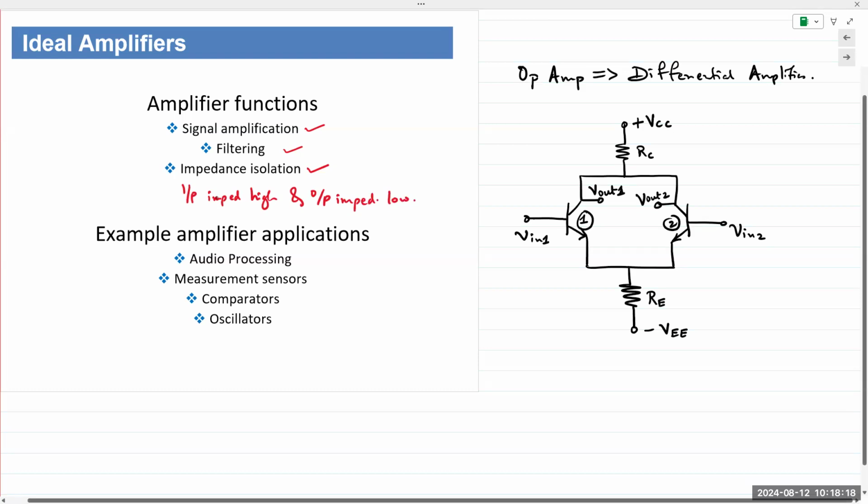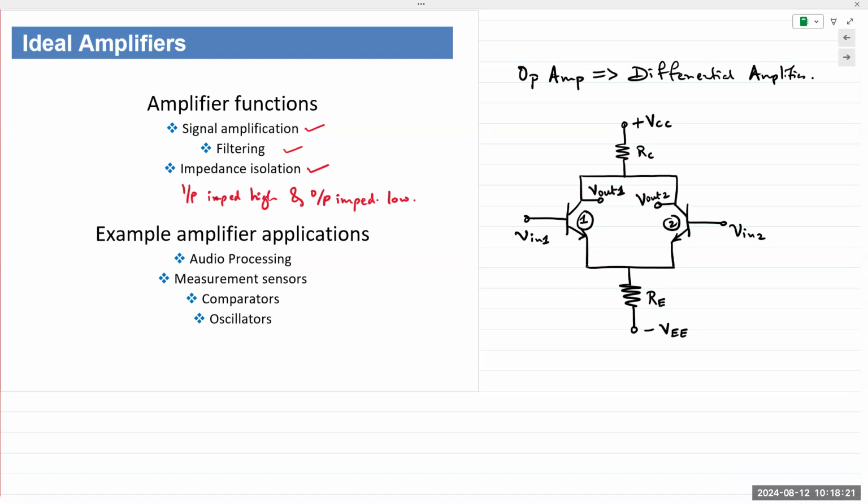Okay. Again, think back to 201. Those of you who took classes with me, I illustrated an example where we match the output impedance of an amplifier, audio amplifier, to the impedance of the speakers. Okay, maximum power transfer theorem. If you want maximum power to be transferred from one stage of your circuit to the next stage, the Thevenin resistance of both should be equal. Otherwise, most of the current or most of the voltage will be dropped inside.